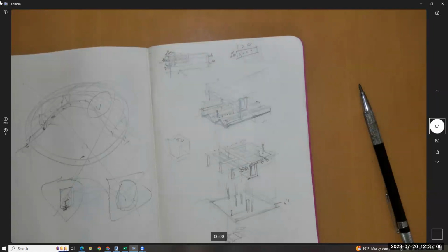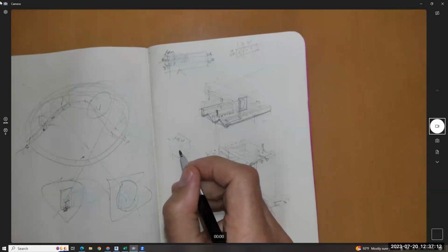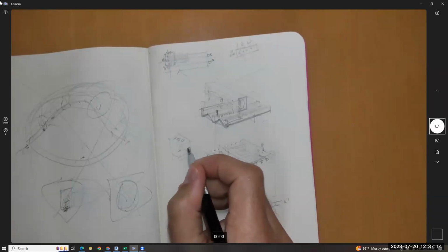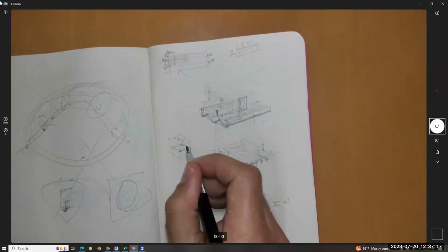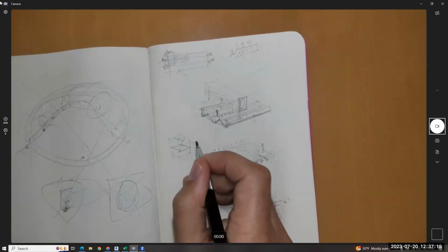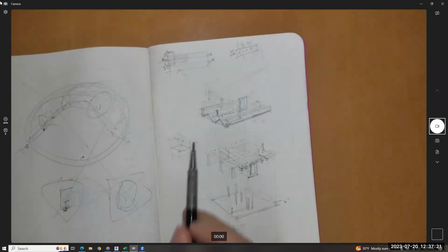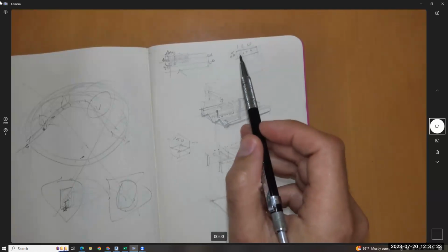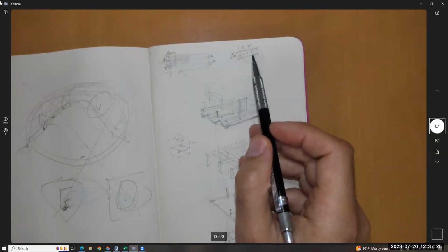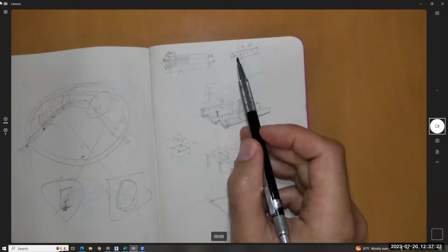So if this is 150 pounds per cubic foot and a slab is 6 inches thick, every square foot is 75 pounds. I could divide that by 2 mentally, or instead of 6,000 square feet, I could just divide that by 2 since it takes 2 of them.